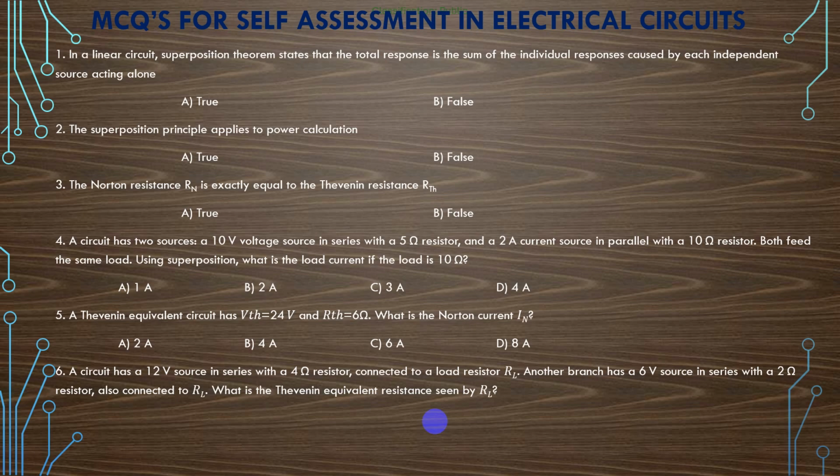Now on the left-hand side, what are there? One voltage source and one resistance. For the voltage source, what do we have to do? We have to short it. If it is a current source, we have to make it open. So this voltage source, 12 volts on the left-hand side, becomes a short, and only 4 ohms will remain.